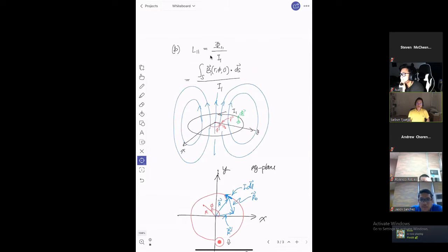Do you know what we mean by self-inductance and what we mean by capacitance? Now, there's no self-capacitance because there's no induction involved. Everything's local. Whereas with the magnetic field, a circuit by itself creates a flux. It can also capture its own flux. If it captures its own flux divided by the amount of current that produces that flux, that will be your self-inductance. Mutual inductance means that someone else has produced a flux and you capture some of it. The ratio of that to your current will be the mutual inductance.